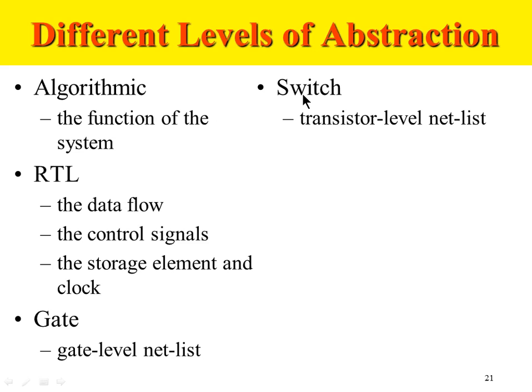So we don't work on the CMOS level. We hardly work on gate level designs, which are structural level designs. This is where we will work, behavioral RTL, to define the behavior of our system using data flow concepts, control signals, storage elements, which are memories or registers, clocks, etc. The algorithmic level is still not used. That is a different part of the languages which is being developed. So this is where we'll operate at a maximum level.